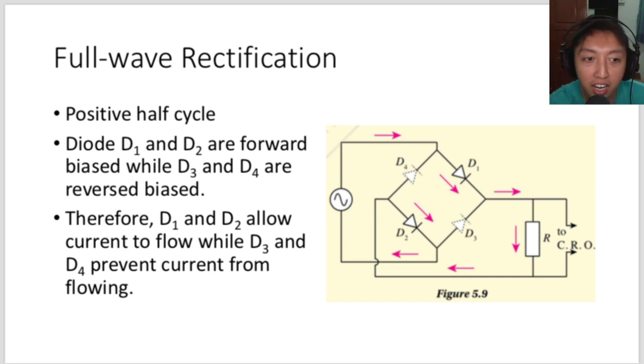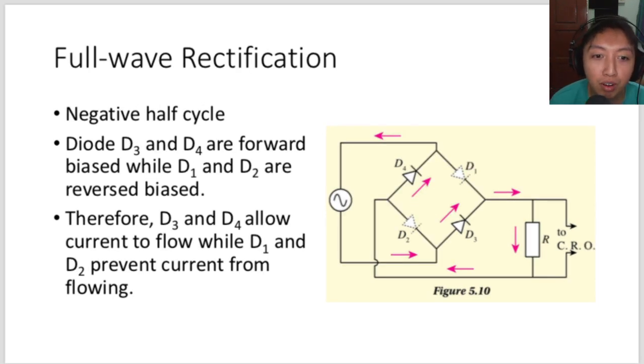Now look what happens here. When we change the direction of the charge, with the negative half cycle, if you look at the lower part, the current is still flowing in the same direction because these diodes are there to control the flow. So we're going in the opposite direction now. It goes down, starting from here. Now you have a choice between D3 and D2. D2 says stop, you're not allowed to go down here. Please go down D3. So we go down D3. Again, you cannot go up to D1. D1 says stop, one way only, please go forward, please proceed.